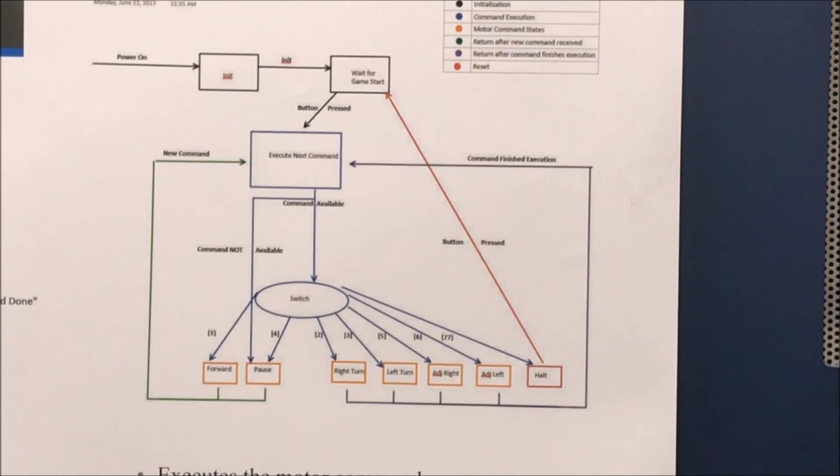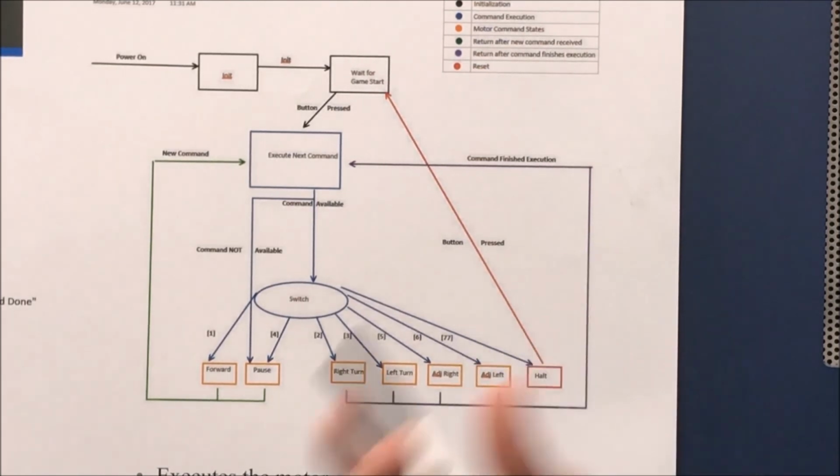One possible solution for this would be to implement encoders on the motor, where you could count the number of ticks rather than simply using a timer and counting the amount of time that the motors are on.